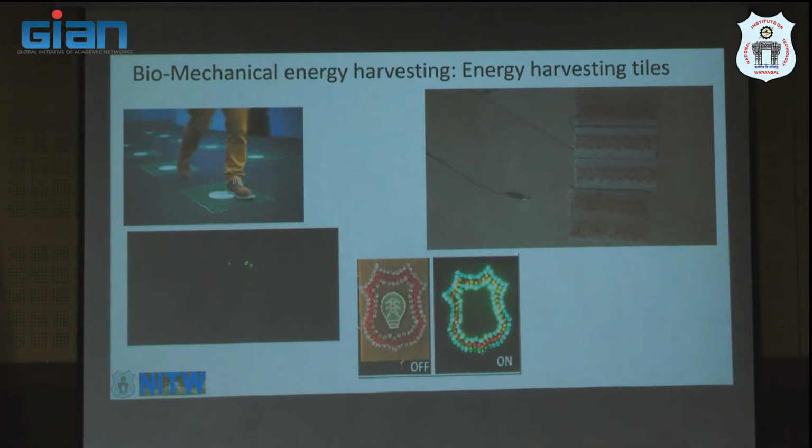No minimum force. Even if you want to use it for a sensing application, even a small touch is enough. Ideally you just need to make a small contact, that's all. If the contact force is more, you are going to get more contact area. You may get a little increased signal, nothing else.